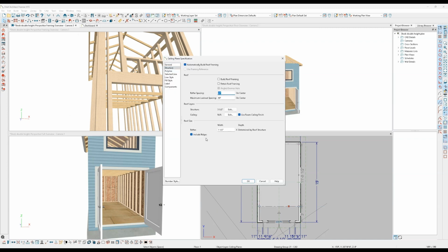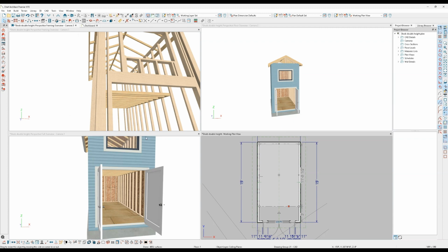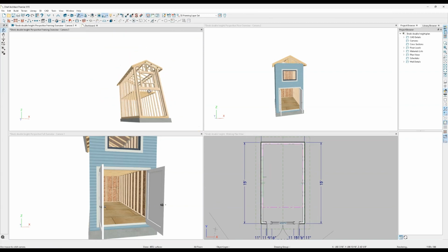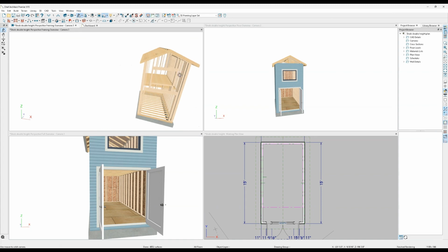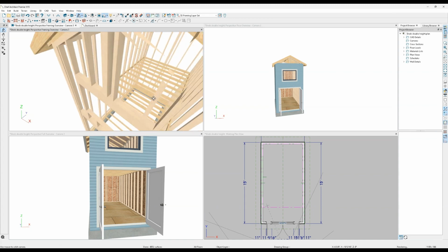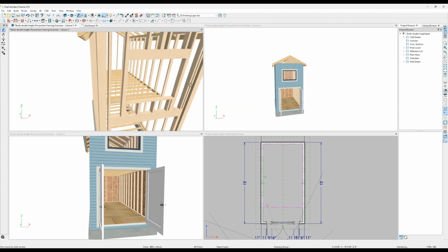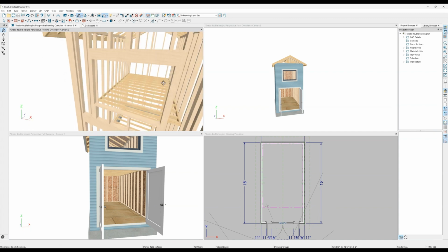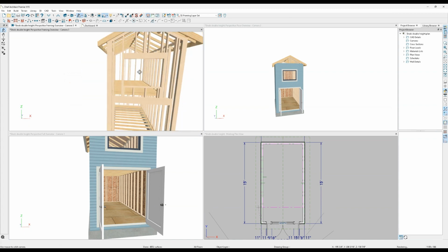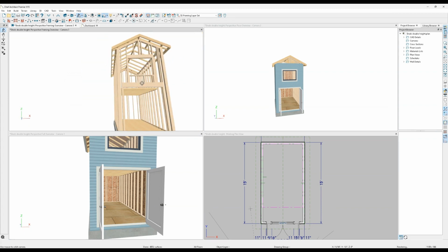We're going to change the spacing to 12. Remember that this is a load-bearing platform that I'm hanging, and all I'm doing is beefing up the spacing so that you get more load and you get less bounciness. These are all 2x4s. It's not expected to carry a vehicle there, okay, so it's just for storage purposes. So there we have it.